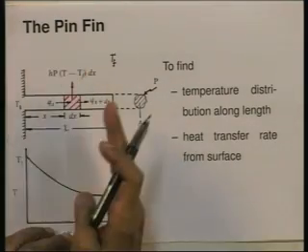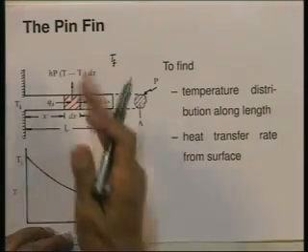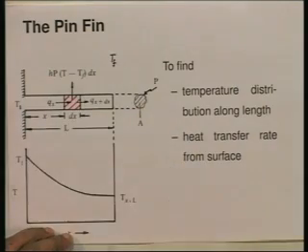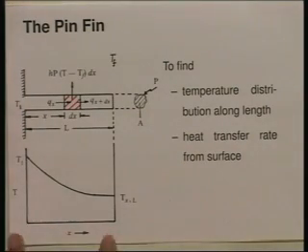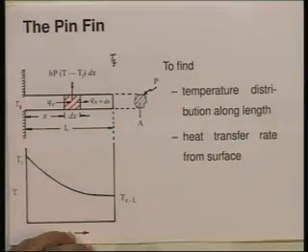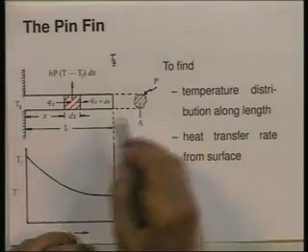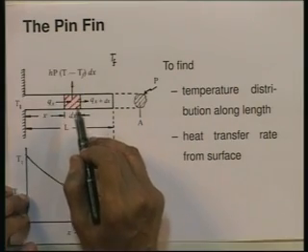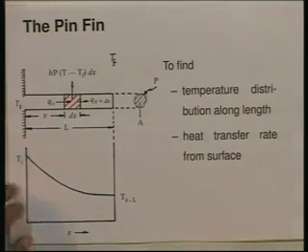That means, at a distance x take a cross section, at a distance x plus dx take a cross section, you will cut out an elementary volume of width dx and cross section equal to the cross section A of the fin, A times dx. Consider the heat balance on this elementary slice of width dx. What do we get? Let us look at that now.